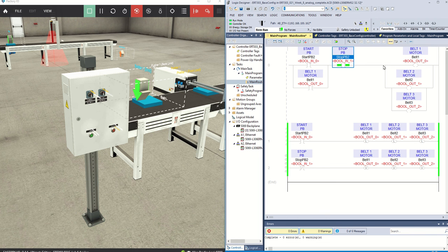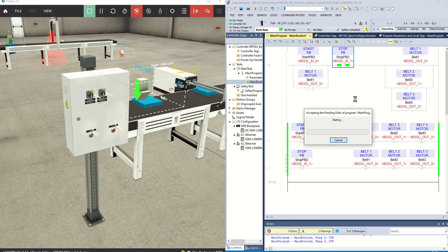So you can see how this is kind of stepped down, and those are actual individual branches there. So this is valid, and this will run. You will see that if you're getting a lot of outputs you're trying to turn on with the same logic, and you're trying to do this for a lot of things, I think this cuts you off after 7 branches.